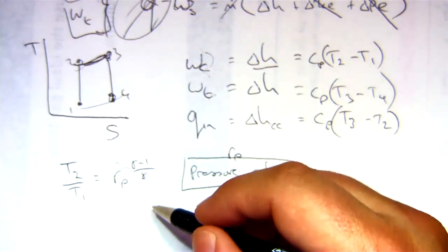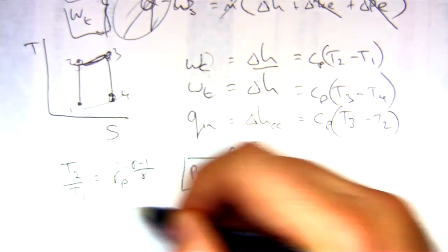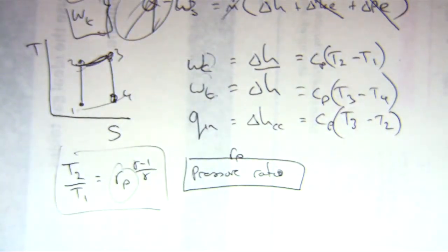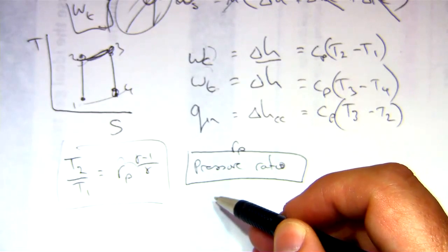What's happened here is that through the isentropic relation, I can determine this temperature. If you remember, I had the PV to the gamma equals a constant equation, and I've got PV equals RT as well. With a combination of those two and some substitutions, you can develop an expression for how temperature changes with pressure at constant entropy. We've also got that S2 minus S1 equation. I wave my hand at this for now to say we will derive this. For the sake of this exercise, let's keep going, and then we'll come back to it.